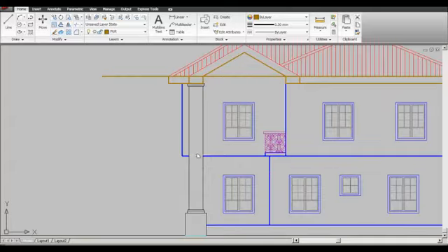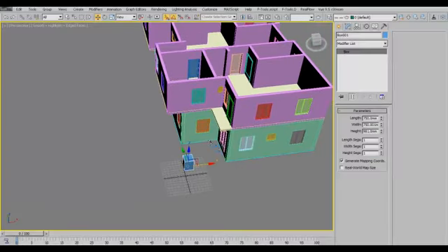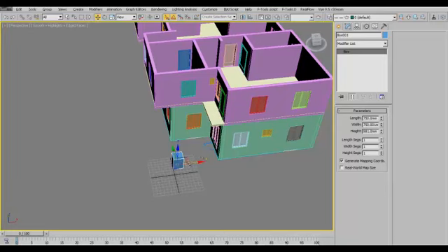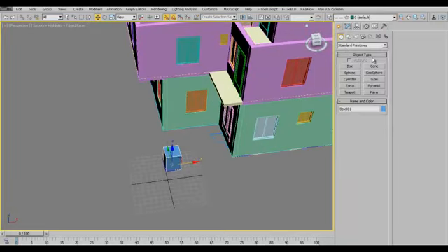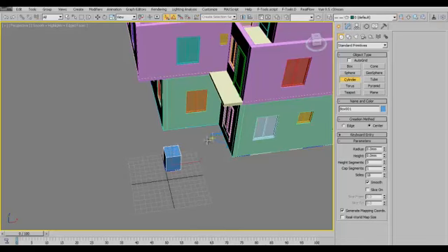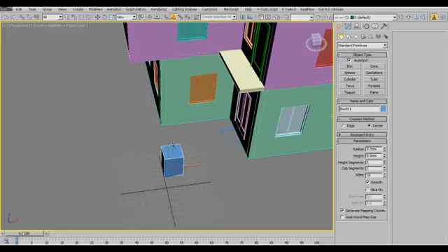And now the major column, which is a round column here, it's a round member. So we could actually use two things. We could actually use a cylinder to create it. We turn off our snap. We turn on our auto grid, which actually grids to a surface of a particular object. You can see what happens if we create it here. It does it this way. We don't want that. If we create it here, it picks the surface as a reference plane to place the base of the object. So we want to place it right here in the center of this.